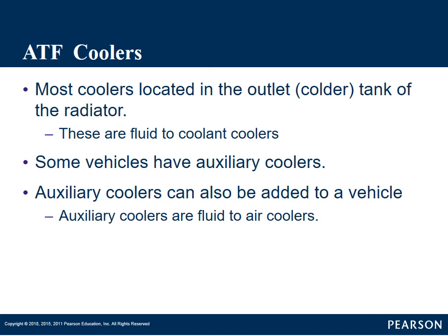These are what they call fluid to air coolers, just like the ones in our radiator are fluid to coolant coolers. They're trying to dissipate the heat from that fluid into that coolant. In auxiliary coolers, they're trying to dissipate the heat from that fluid into the air that's flowing over the cooler.